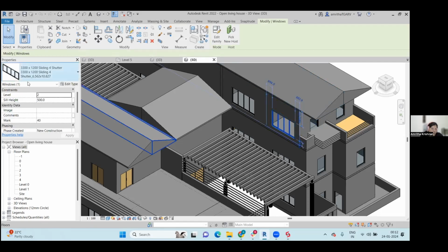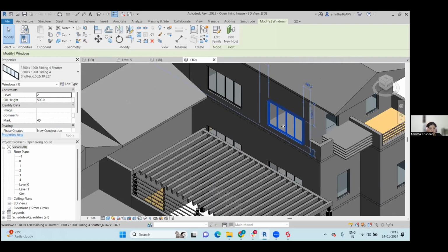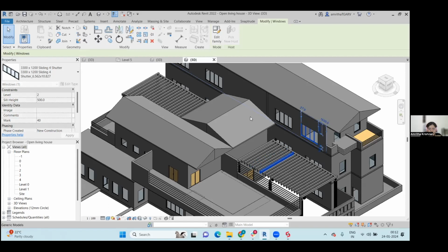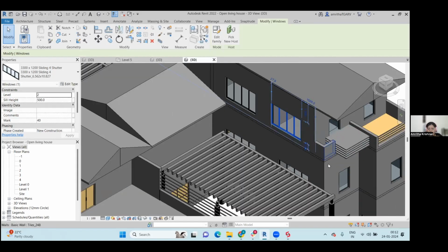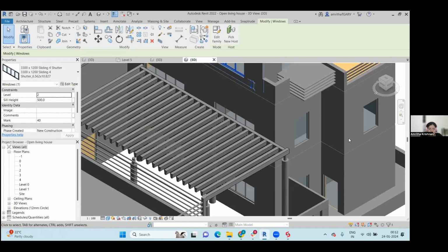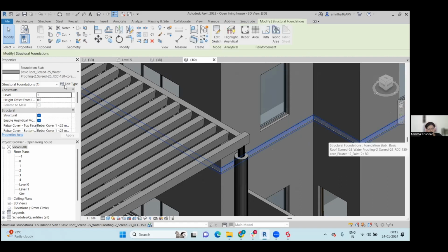The ones that are parametric, you actually get RFAs for all of your doors and windows. So the Revit export is more powerful than using something like an IFC export, right? So at this point, if I wanted to move my window along inside of Revit, you can do that as well. All the family information is really well preserved as well.